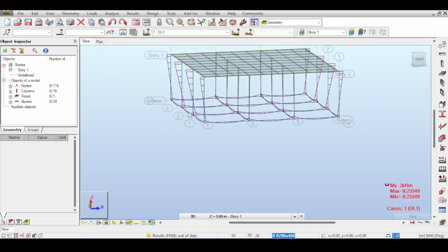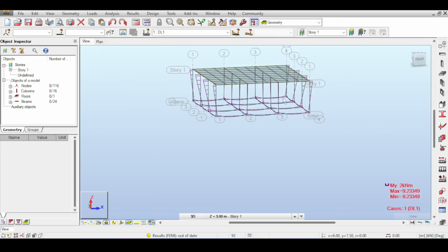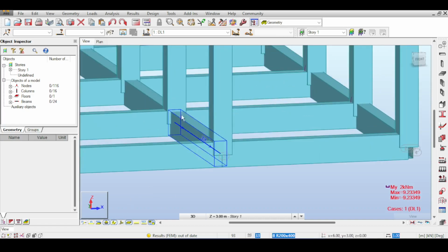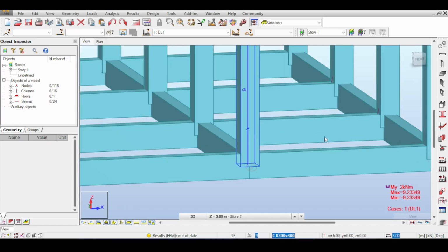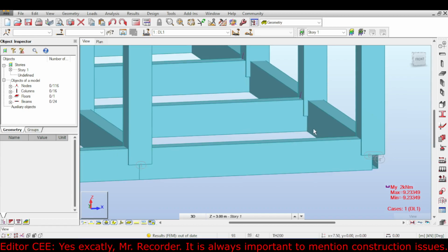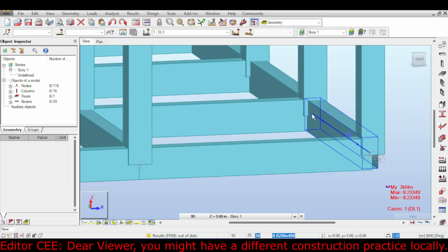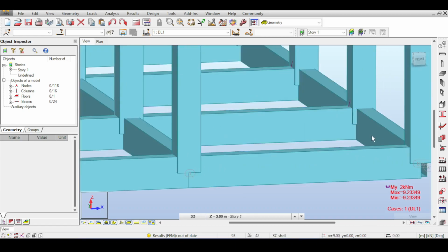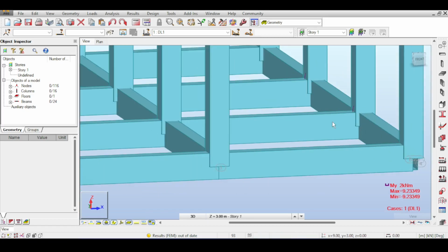Also, our structure is embedded in the ground, so it's pretty hard to move it. Also, having a beam like this means that it anchors itself into the clay. How do I construct this? The surface of the clay would go up to the height of the beam minus 20 centimeters, because you're going to put your slab or your raft here. So I'm kind of not convinced that this will move.